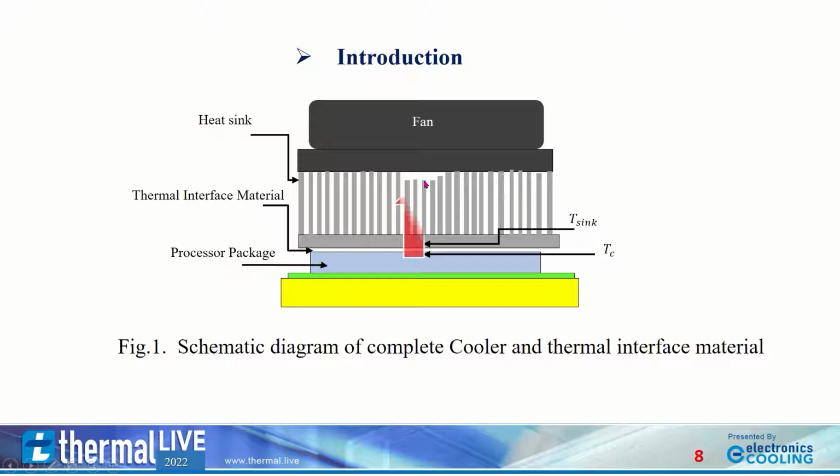When the CPU cooler is attached tightly to the CPU, the heat transfers from the CPU to the heat sink, and finally heat is dissipated by fan forced convection. Traditionally, the CPU cooler includes a fan and a heat sink. But more strictly speaking, it should include a very good TIM material between the bottom of the heat sink and the CPU surface, as shown in figure 1.